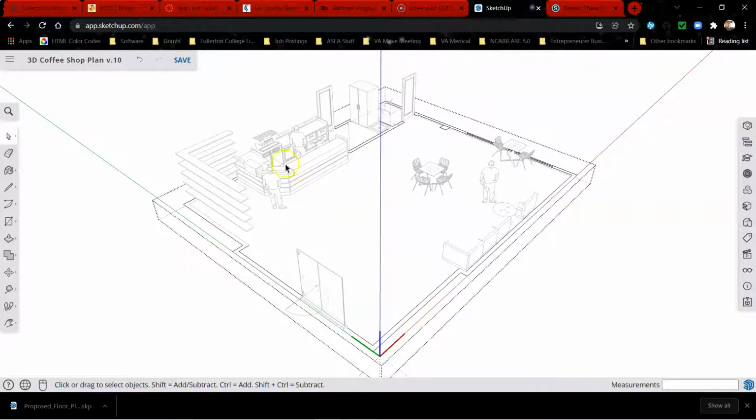Notice how this is all grayed out. And notice how this box right here, this is that force field that's around the component, protecting these lines. But since we're inside of it, we can manipulate. Alright, so now we're going to use the push-pull command, the letter P. And this is the push-pull command.